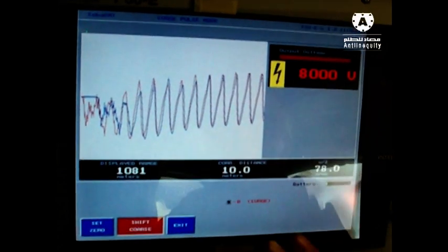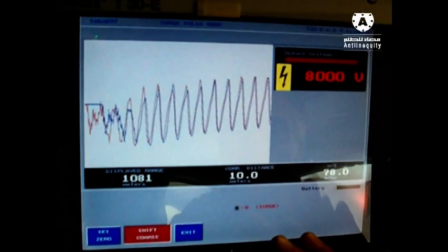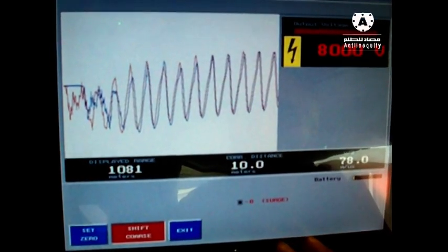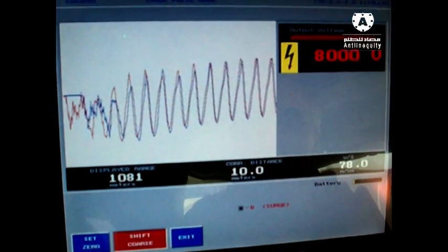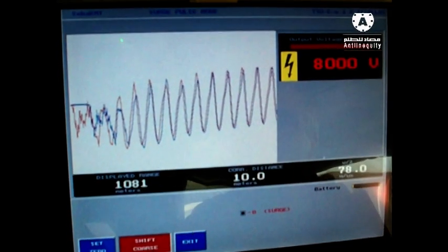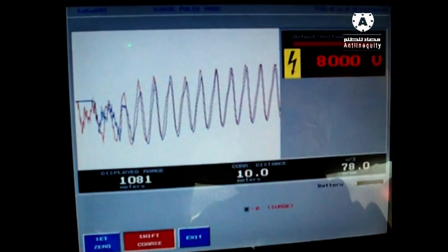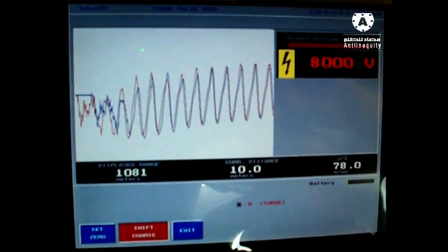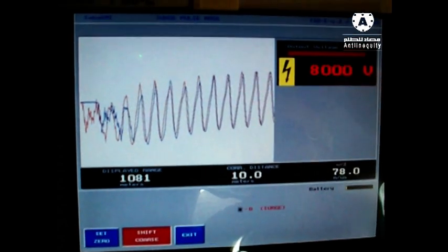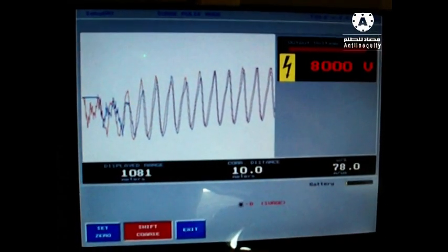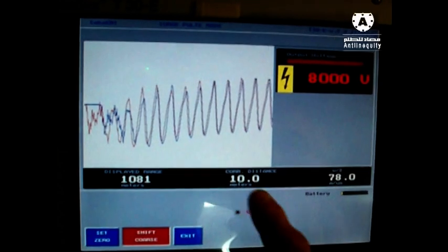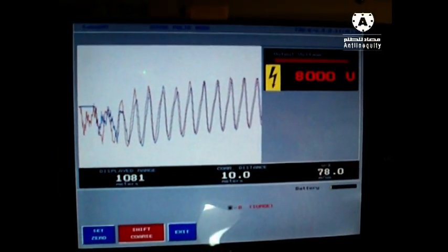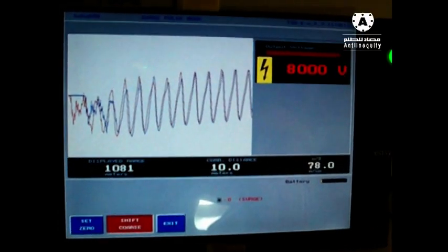This is not a really good sample because we set a 0 point. The 0 point means the system is calculating the length of the fault from the cable end of our high voltage cable drum, from this connection point to the real fault. But in our case it is the same point. That's the reason why we don't have a big distance to our fault, because it is still at the end of our high voltage cable drum.